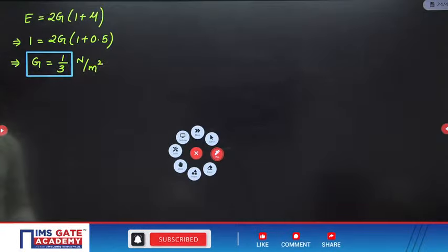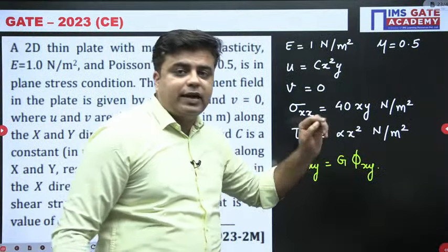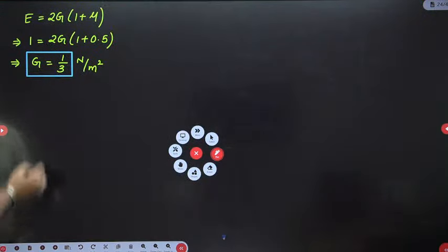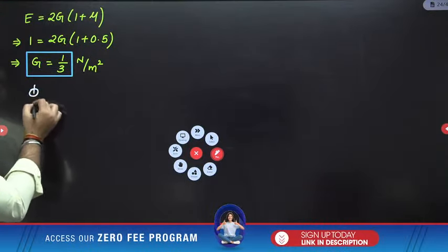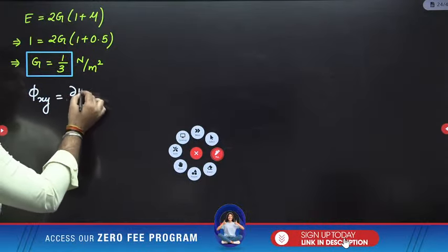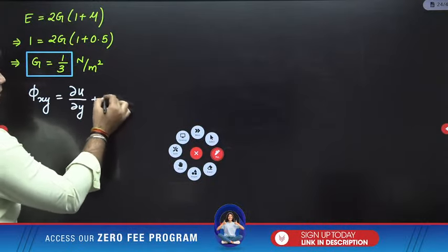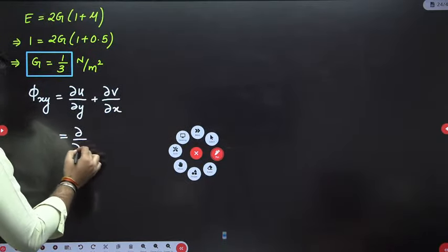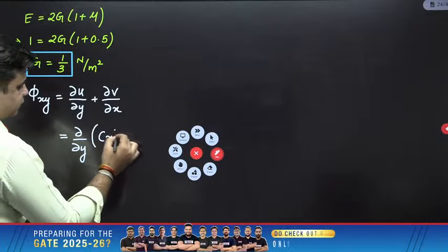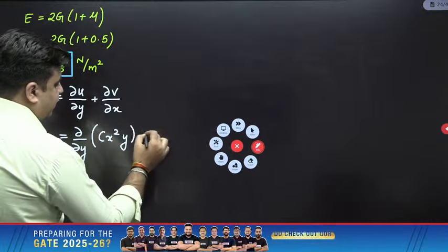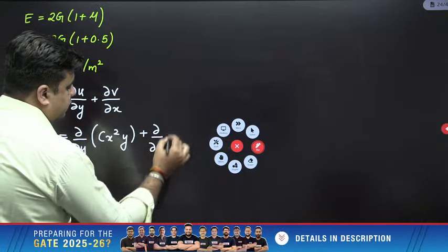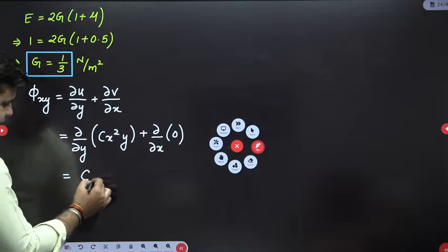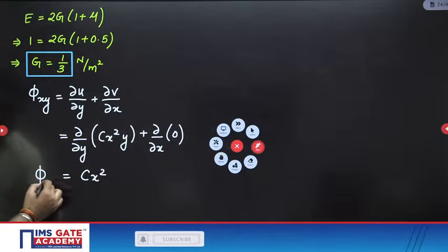Then, sir, do I know the value of phi xy? Yes, sir, I very well know the value of phi xy because I know the value of u and v. So phi xy is equal to del u upon del y plus del v upon del x. Please substitute the values. So you have del upon del y of Cx square y plus del by del x of 0. So this term will be 0. This term will be Cx square. So the value of phi xy will be Cx square.